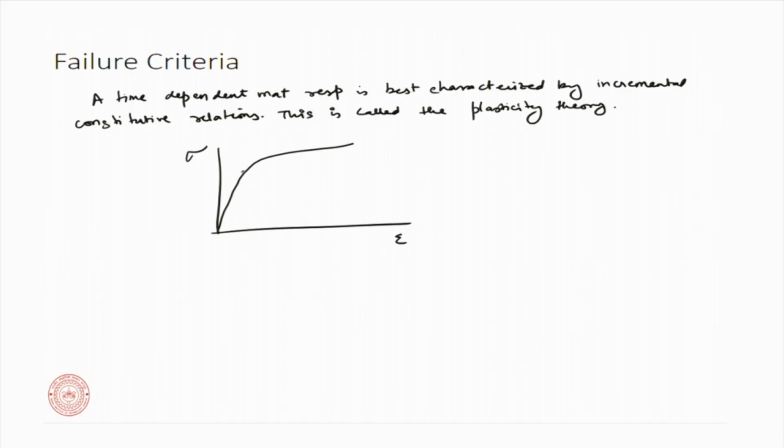like this, then up to this point is your elastic condition, sigma y, and beyond this point is your plasticity. So, if you have a point over here, you will come back following the same slope, that is E, and this will be your epsilon p, that will be your residual plasticity in the material. This phenomenon is called hardening, in which the material hardens and then the material can actually come down, and that is called softening. Okay, so this is the behavior for a ductile material.